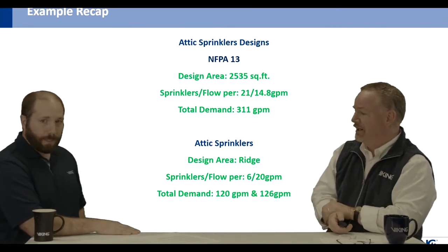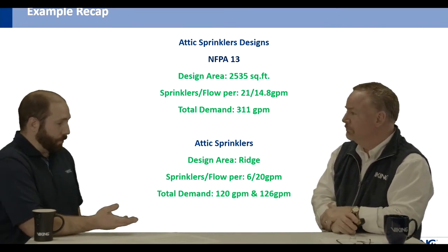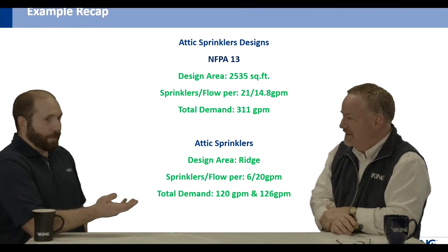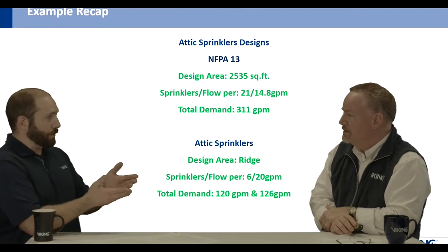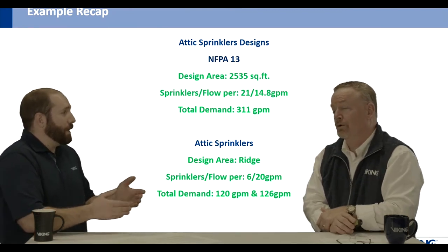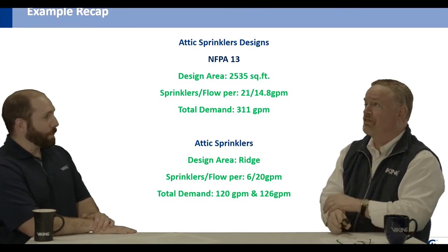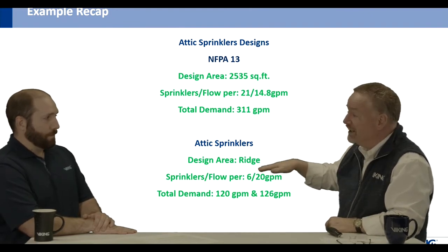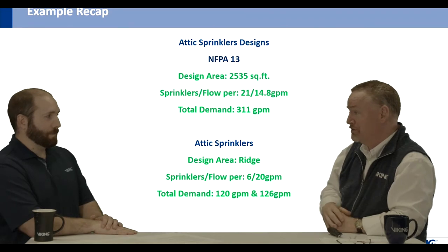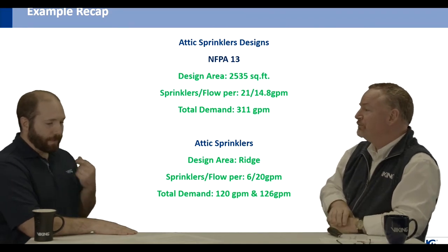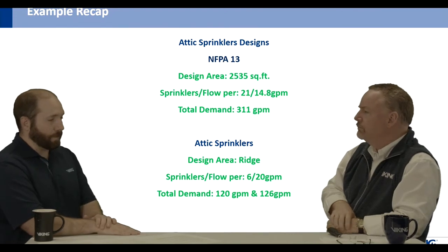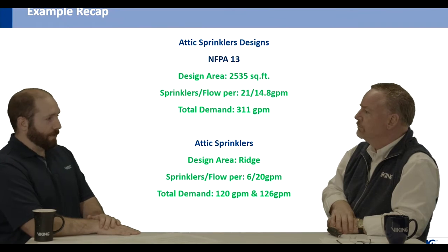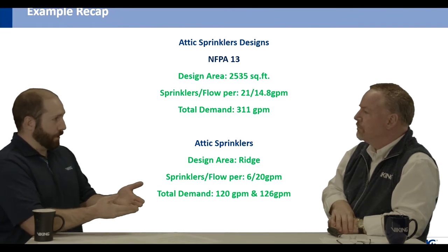Yeah, absolutely. There's another common question. It's kind of an interesting and a cool concept, but it's not anything that we've tested for. Can attic sprinklers be used in, like, open gymnasiums or churches? Something that represents the same slope of the ceiling, but there's nothing underneath it. It's not a concealed space. There's stuff underneath there. Correct. So it's a specific application sprinkler using the attic sprinklers. They have certain criteria laid out in UL. So the standard is going to call for a roof. It's going to have trusses or joists.